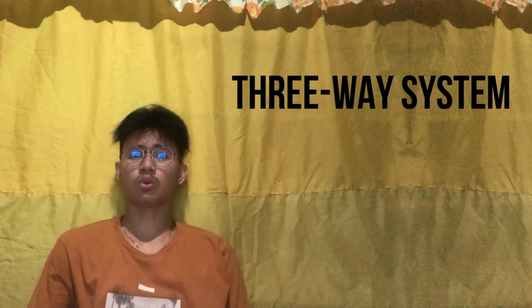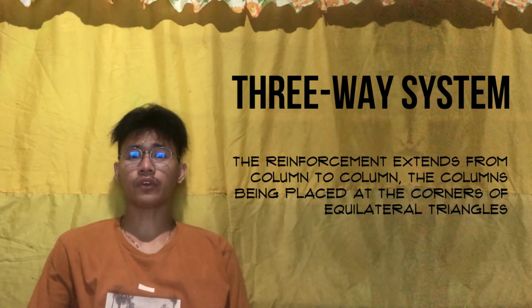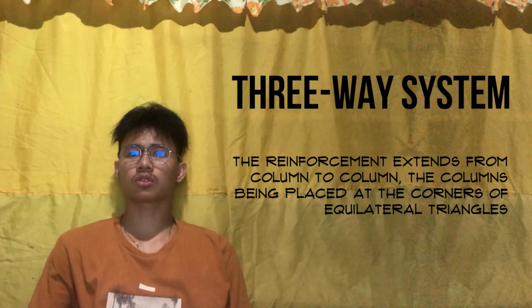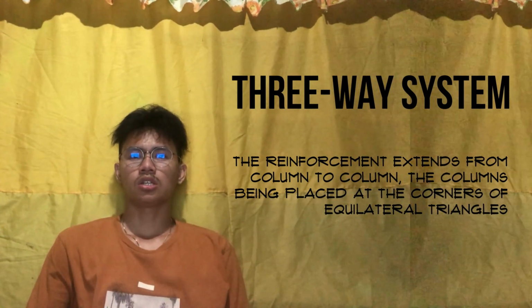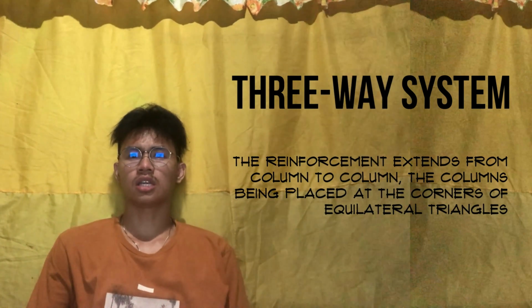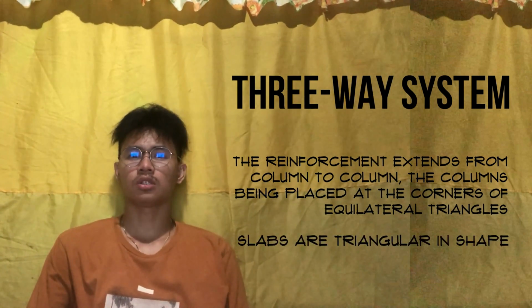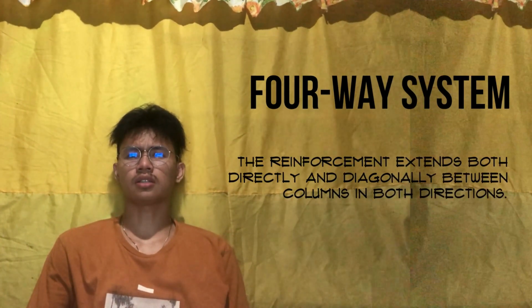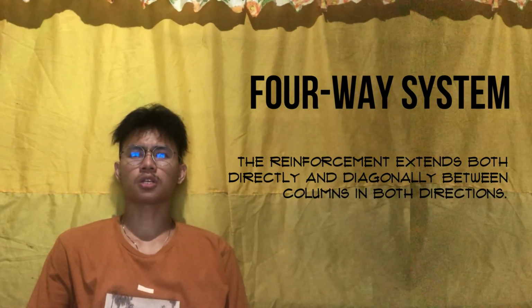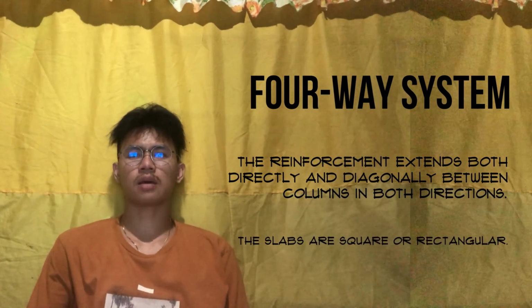Number 2. Three-way system. The reinforcement extends from column to column, the columns being placed at the corners of equilateral triangles. Hence, slabs are triangular in shape. Number 3. Four-way system. The reinforcement extends both directly and diagonally between columns in both directions. The slabs are square or rectangular.